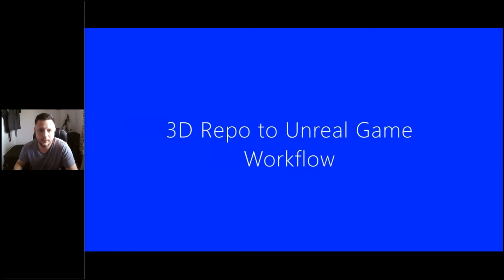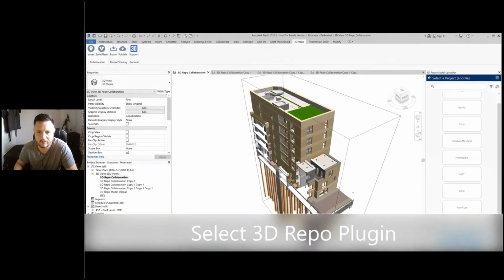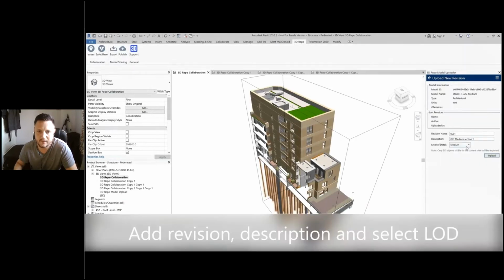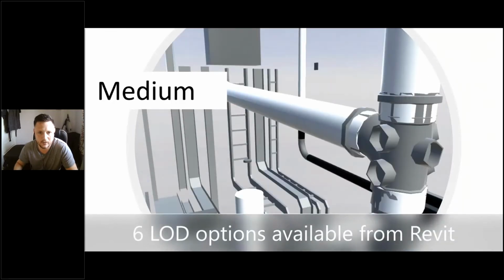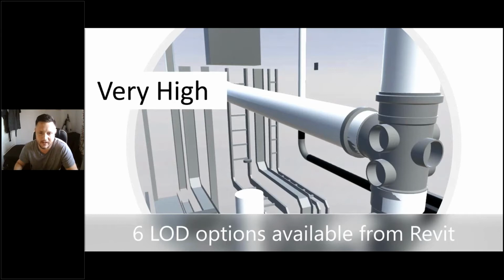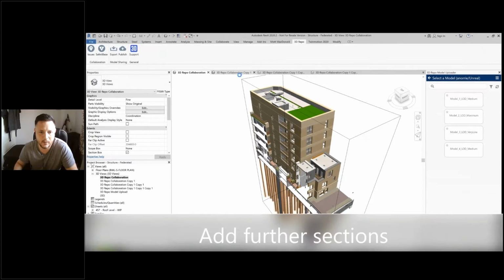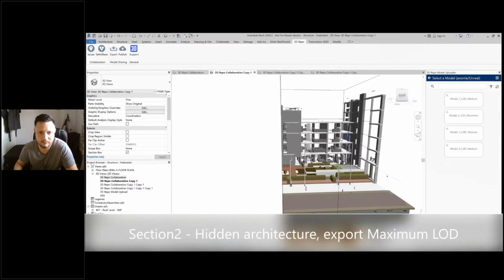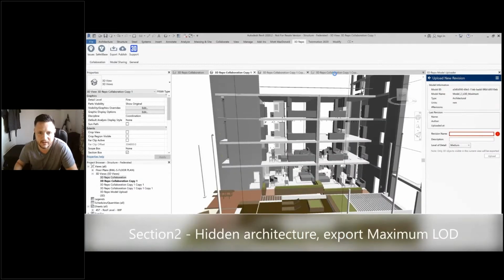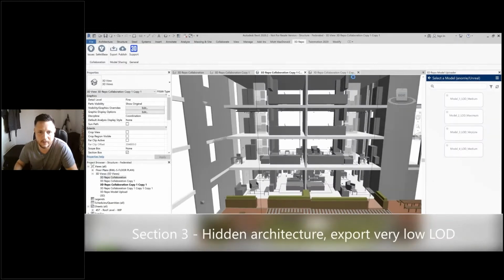So in terms of the workflow, this is an example here of the Revit workflow. Within Revit, we have a set of plugins for 3D Repo, so we can come in here and set the level of detail of this model that we want to put in. So we can go from very low all the way up to a maximum. This is useful if there are certain areas of the model that you don't need that really high fidelity modeling, to keep it lightweight. So we can upload that section to 3D Repo and then create another section. This time we'll hide the architecture and we'll change the LOD, and again go through, change the LOD again in another section, and then a final end section.